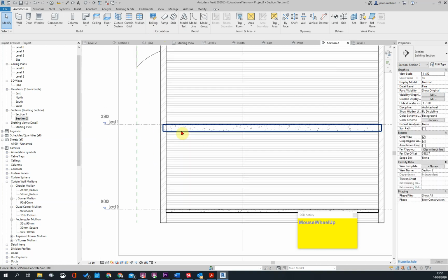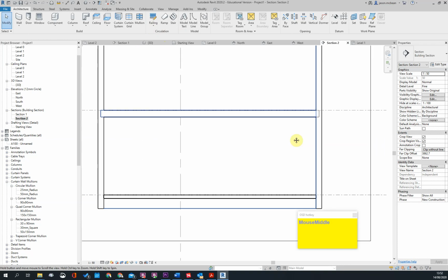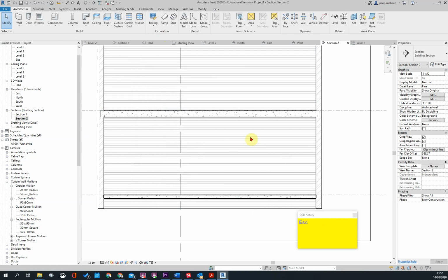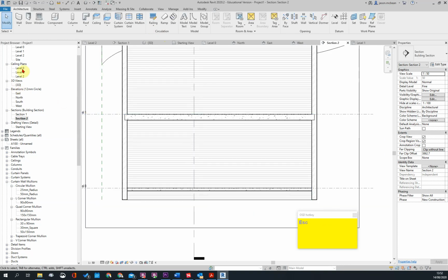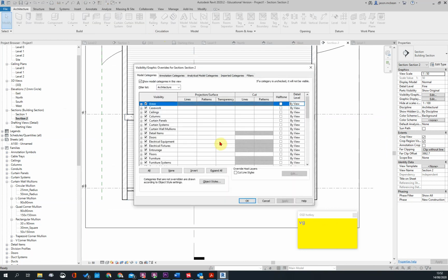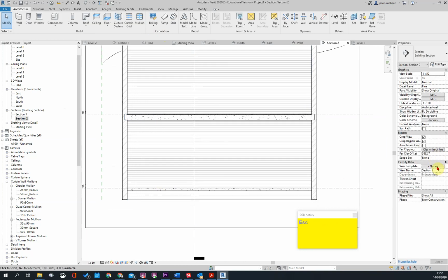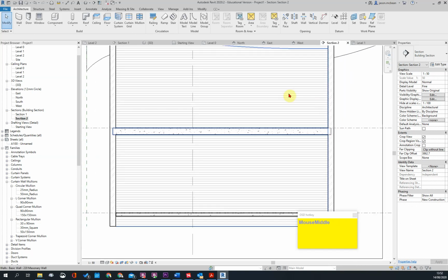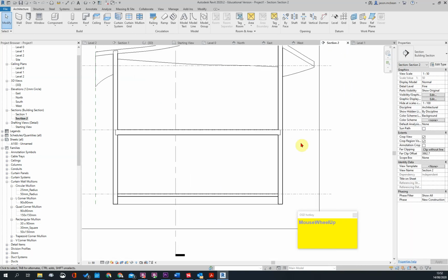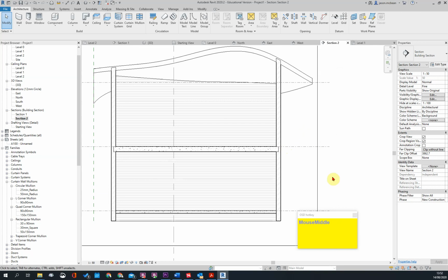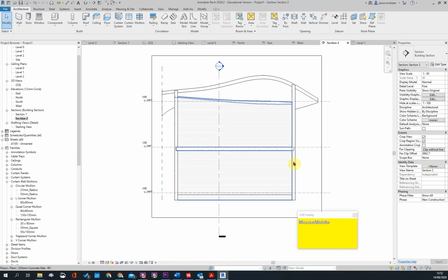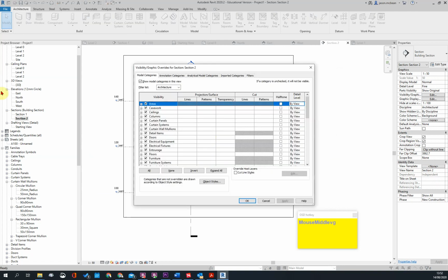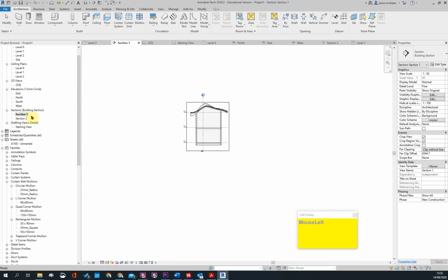Okay. I'm just quickly going to join these two and then overwrite my view. Just as a quick note, interior students, you'll notice that in my plan here, you can use a view template to drive your elevations, and I'll explain that quickly because if you've got my model, you'll notice that some of the settings are locked. Let me go to this section here.